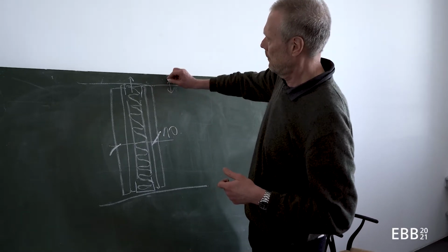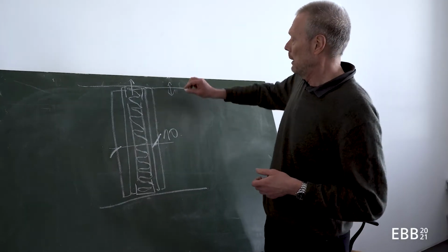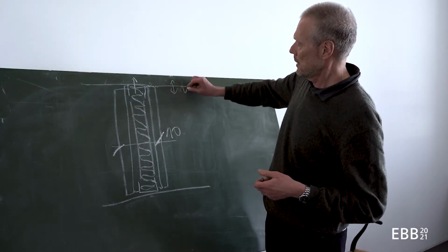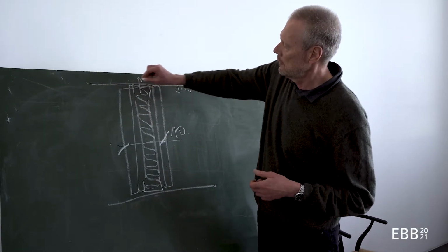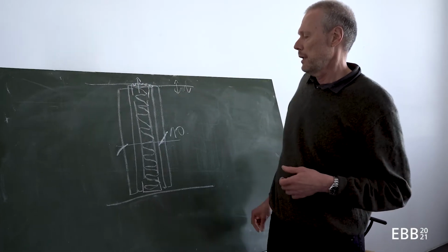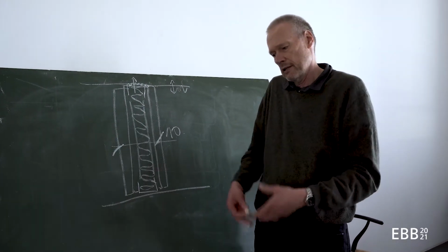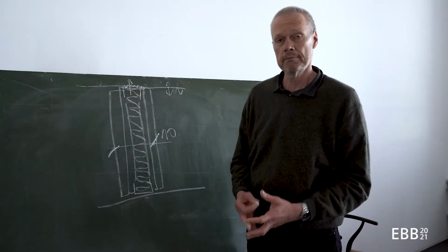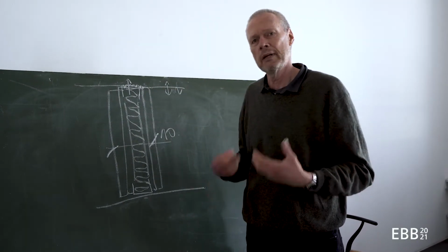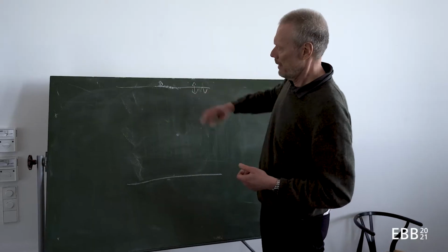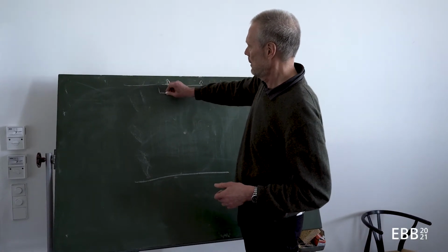So if, for example, this ceiling here can move, and this might be 2 centimeters or so, then I have to guarantee by integrating insulating materials that can take a certain movement of the ceiling, so that I won't have cracks inside my non-load bearing wall.